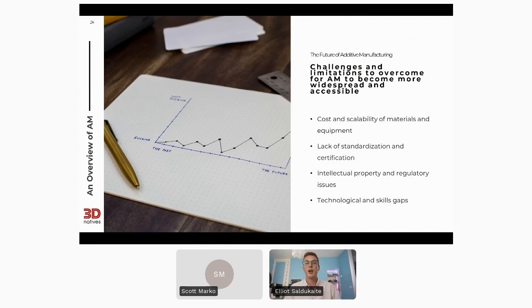Also, additive manufacturing lacks in terms of standardization and certification, especially for applications like aerospace, automotive, things where safety is a big preoccupation. We are lacking regulations and certifications, whether that be of the material or the actual process itself, to allow for the use of these processes.